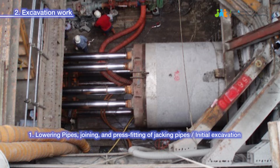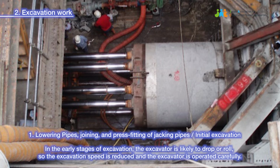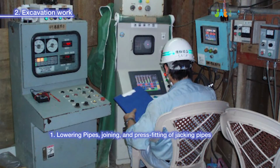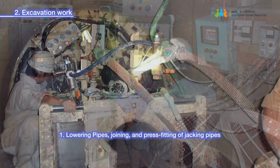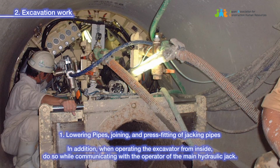Initial excavation. In the early stages of excavation, the excavator is likely to drop or roll, so the excavation speed is reduced and the excavator is operated carefully. Depending on the construction conditions, the excavator and main hydraulic jack can be operated remotely. In addition, when operating the excavator from inside, do so while communicating with the operator of the main hydraulic jack.